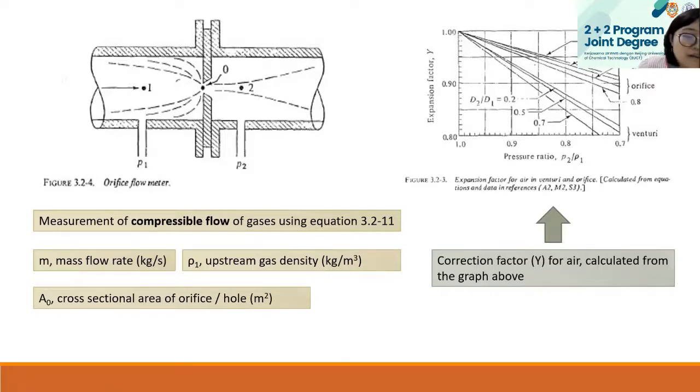So it's similar to Venturi. That's for the incompressible flow. While for the compressible flow, let's say the flowing fluid here is air, which is compressible, we can use this equation for the measurement. Again, it is similar to what we have learned in venturimeter.